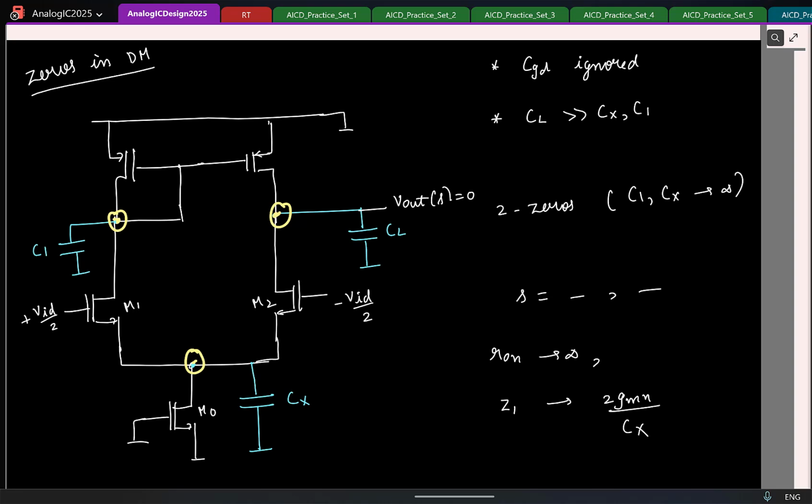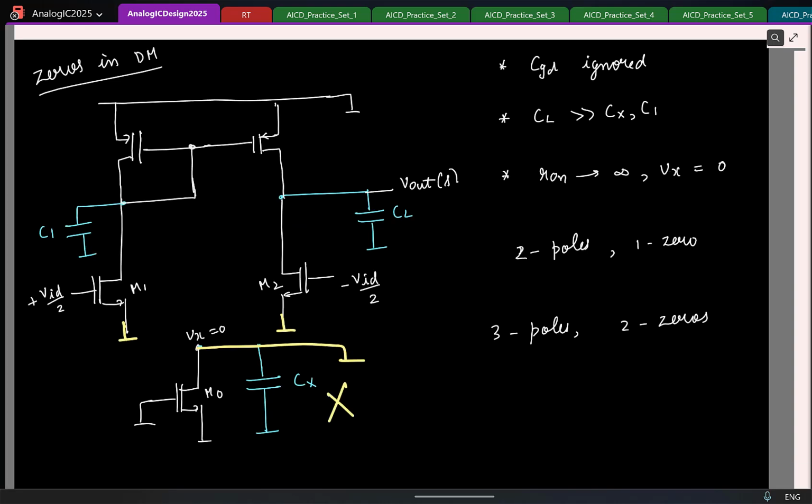So that's a special case where you ignore the R0 of the NMOS transistor here. Then you will have this. This is again an example of an uncontrollable or unobservable state, where you have an exact pole-zero cancellation. But strictly speaking, the circuit has 3 poles and 2 zeros, just that in this particular condition, one pole and 1 zero fall on top of each other.